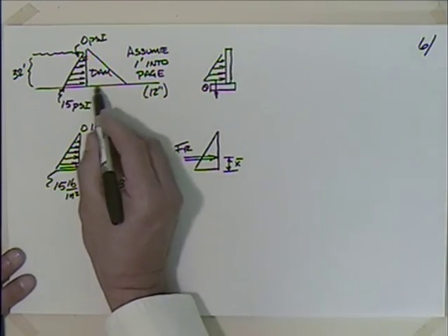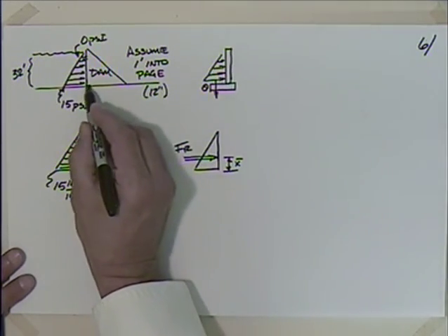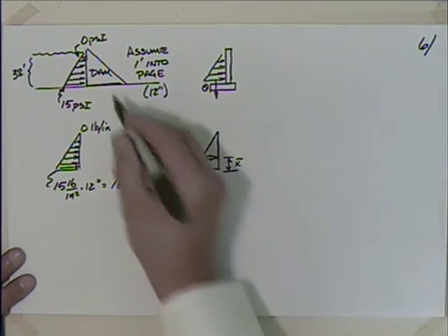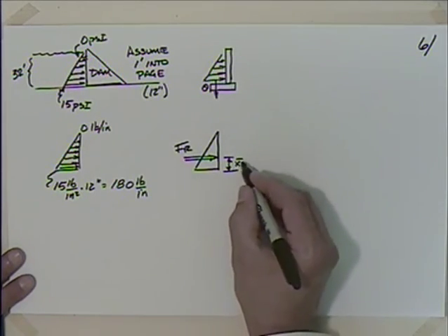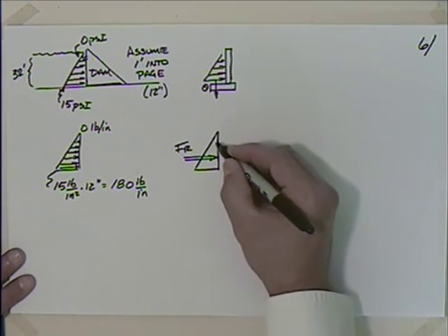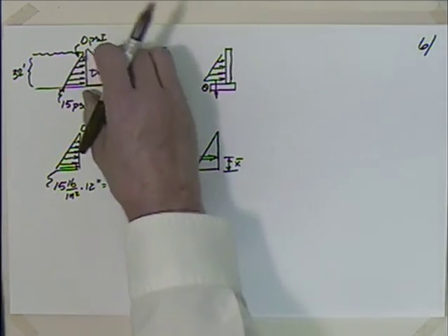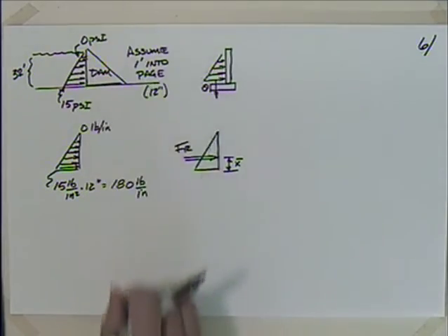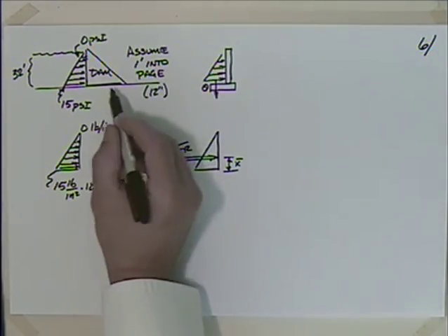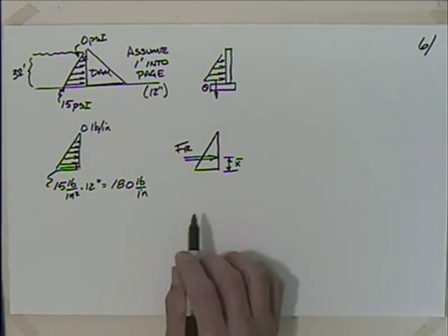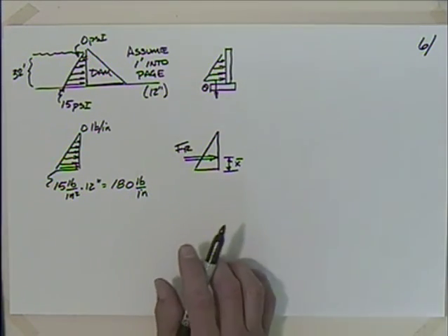You don't want the dam to slide down the valley. That's a big problem. And this x distance is important if we start talking about the moment and talking about the dam turning over. You don't want the dam to turn over, to tumble. That's a bad day, and you also don't want the dam to slide down the valley. So both of those numbers are important.